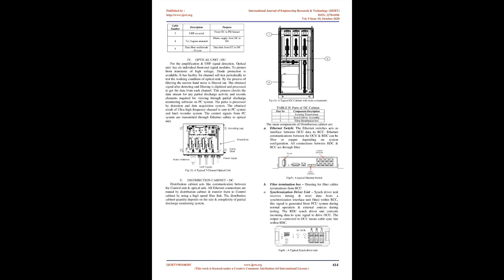Gas-insulated switchgears in general for transmission substations follow the double-bus single breaker scheme for 110 kV or 132 kV and 1.5 breaker scheme for 380 kV or 400 kV substations. Typical GIS photo for 380 kV GIS is as below.